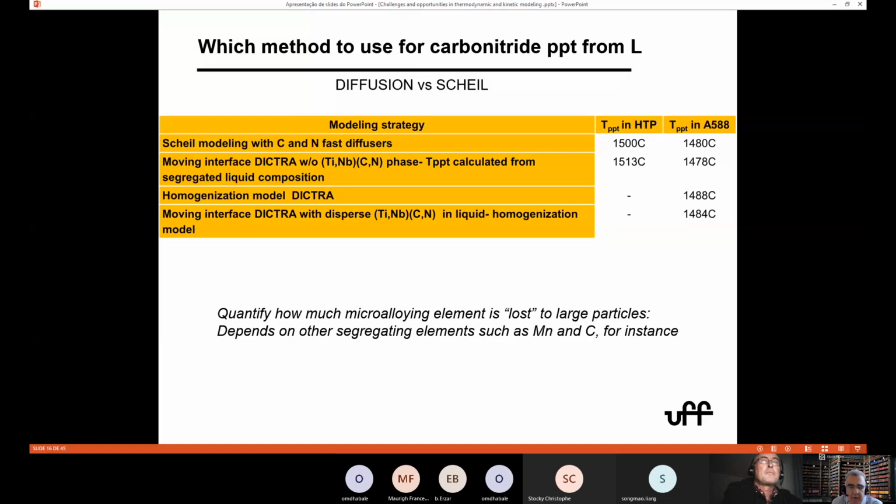And you say, well, I'm losing vanadium or I'm losing titanium. This is not like losing a little bit of manganese. The price scale is completely different. So you have to be very careful. There's no point in adding a lot of manganese, which is cheap, and then adding a little bit of vanadium and titanium and niobium, and then losing these things. It doesn't make sense. You get it in the heat analysis, but it's not doing what you're paying for.